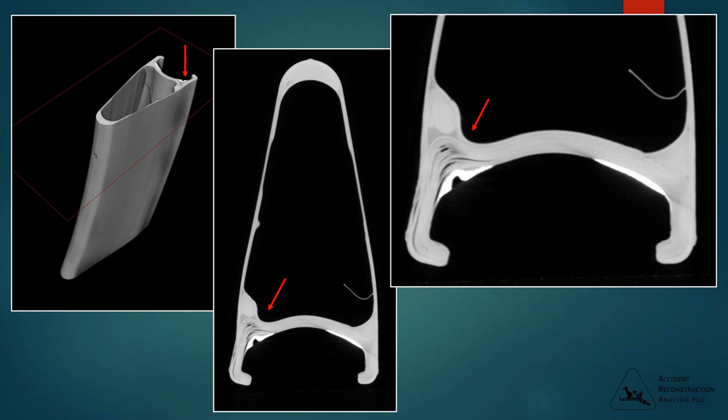It's obvious in the center image that the sidewall of the rim has bowed out and was probably responsible for this rim hitting the brake pad on the bike. And if you look at the corner on the other side, there's no apparent delamination. And again, a higher magnification image of the delamination at the right.